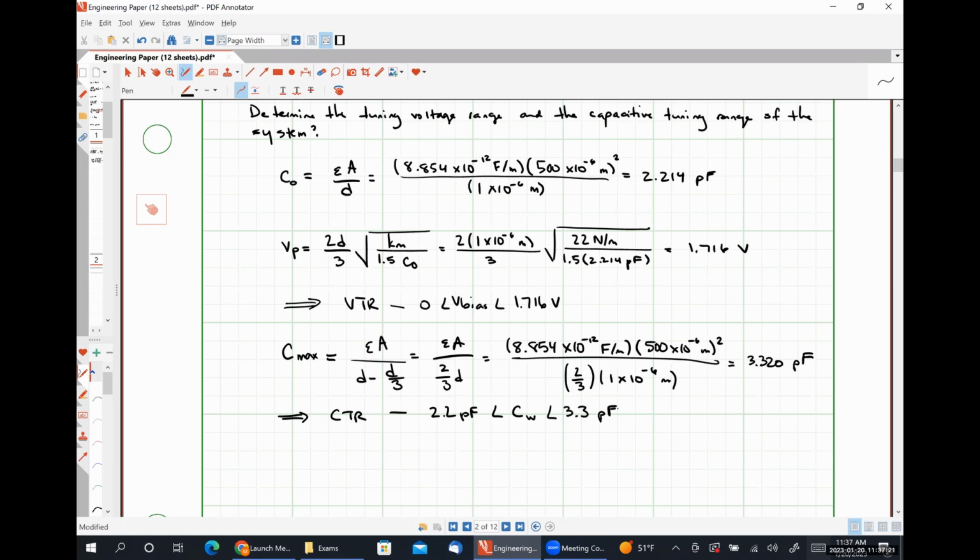There were several iterations on this design that tried to extend the capacitive tuning range. Fundamentally, it was limited to 50% before the pull-in effect happened. So they put insulating microstructures in between the plates so that when pull-in happened, your plate would hit that insulating structure and then would bend, giving you a greater tuning range.